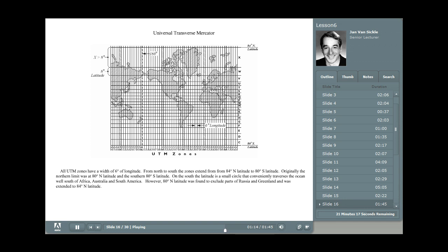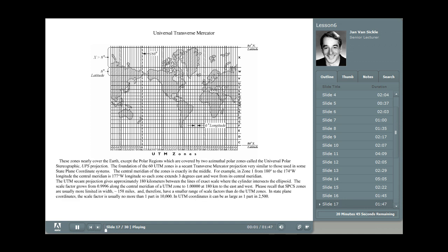The reason I point this out is because there are GPS systems that use these letter designations along with the number of the UTM zone to identify a particular quad in this picture here. Like, for example, C21 would be the square that you see just immediately above 21 in the southern hemisphere. This is a useful method of referring to a particular quad in a particular UTM zone, and is used also in the military.